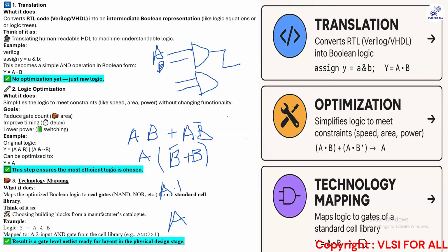Pardon? Why don't we give? I said libraries have to be given in the form of different MMMC, right? That is not a single .lib file. If you would have done your project and look at the .lib file, you have to give this .lib file for MMMC, all the multi-corner modes, correct?